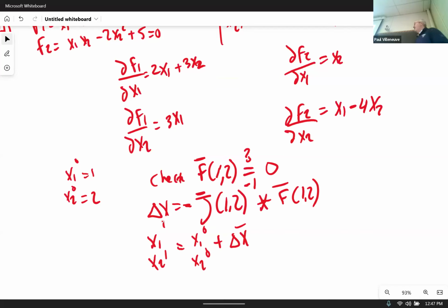And with that, that should have been an indication for problem number 6. Given a 10-bus system, what is the maximum number of equations that you can write? 18, right? If you have to have a slack bus, you can't write 20 equations. You've got to write 18. And what's the minimum? Well, you have to write at least one equation, right?